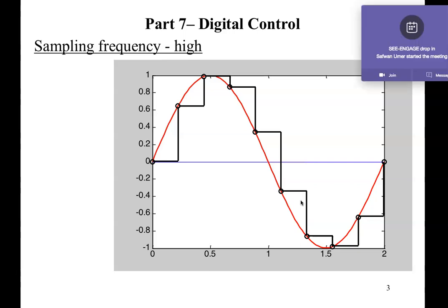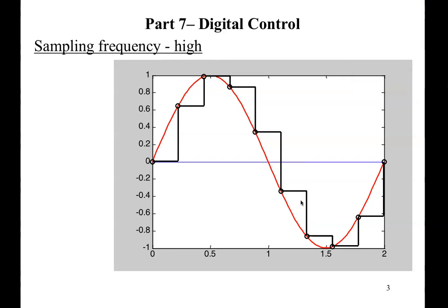Now, in our design, we did try to find a design system that will give us a good phase margin. Now, just because we introduce this digital system and you lose 20 here, that is a lot in feedback control. So we need to be very careful with the selection of the sampling interval. There are two issues here. One is the attenuation, the other one is the delay.